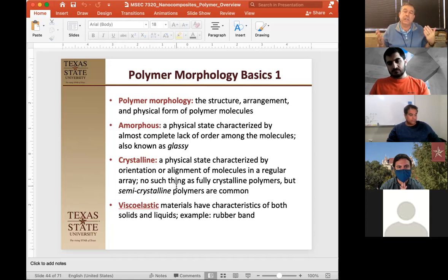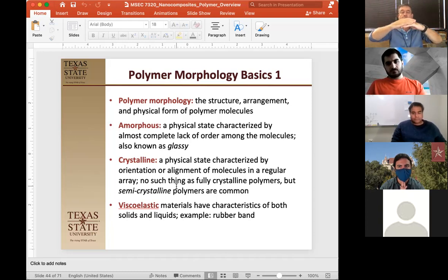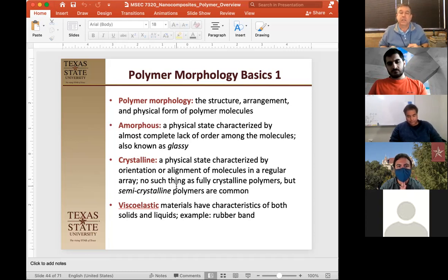And especially if the polymer is a rigid polymer but has no crystalline sections to hold it together, we call that a glassy polymer or a glass. Because it's not crystalline, because it's amorphous like glass is in its plate glass state, we call it a glassy state because it's not in a rubbery state. The rubbery state is when it can move. The glassy state is when it's fixed but still doesn't have crystals in it.